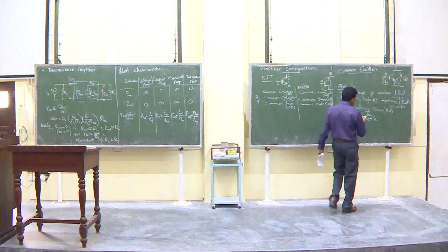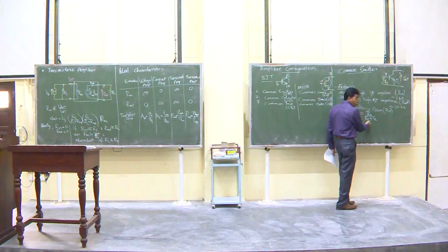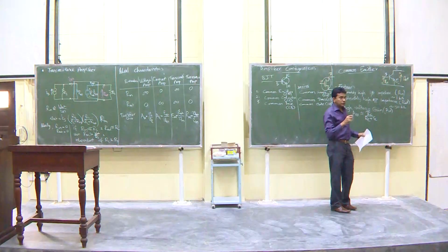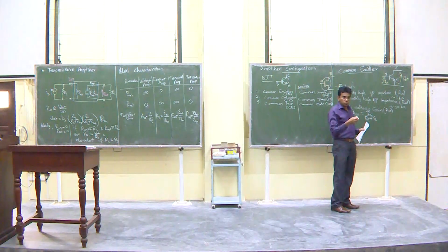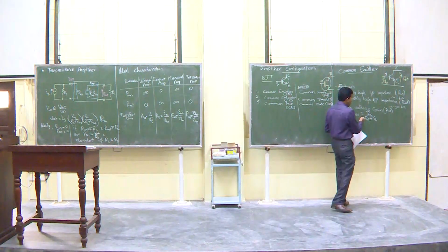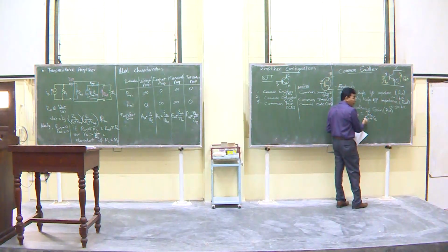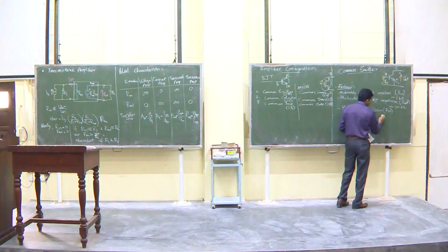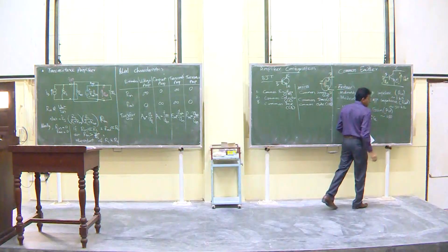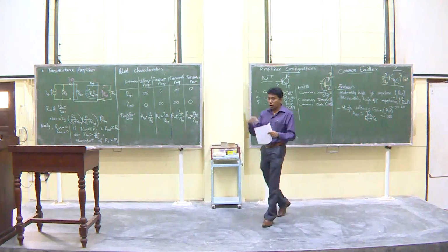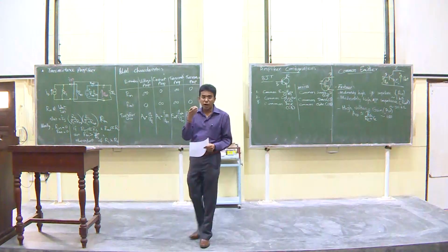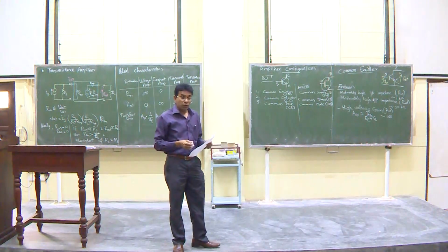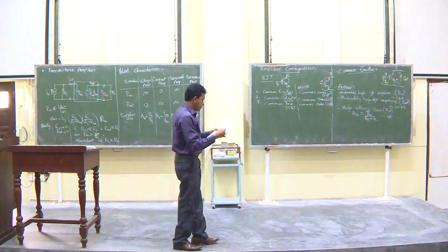This typically, I said these are small values. RE is in the range of maybe about 100 ohms or something, right? Anyways, what we put here is a small value, even the example that we had was a small value. So this ratio is big, like 100. 100 is a high gain. So 1 millivolt turns out to be 100 millivolts. So it's a big value, right?